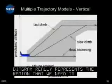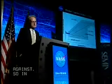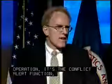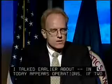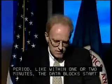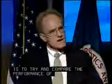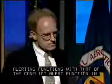So in today's airspace operations, it's the conflict alert function, which is kind of a safety net for controllers. I talked earlier about, in today's operations, if two aircraft are predicted to lose separation within a short period, like within 1 or 2 minutes, the data blocks start flashing. So the approach we've taken here is to try and compare the performance of our safety alerting functions with that of the conflict alert function in today's operations. Next slide.